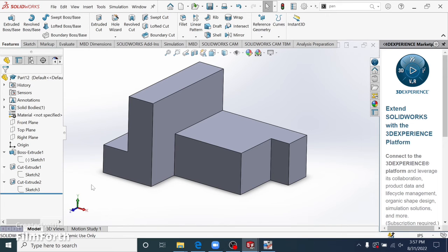And another heads up is that you have to keep going back and forth, back and forth, back and forth. The first one is going to be sketch 1, you're done with it, go back to features, then you do your extrude. Go back again, go to sketch, you make sketch 2, then you do your design, go back and exit, go to features, then you do your part, go back again to sketch. You get the idea now.